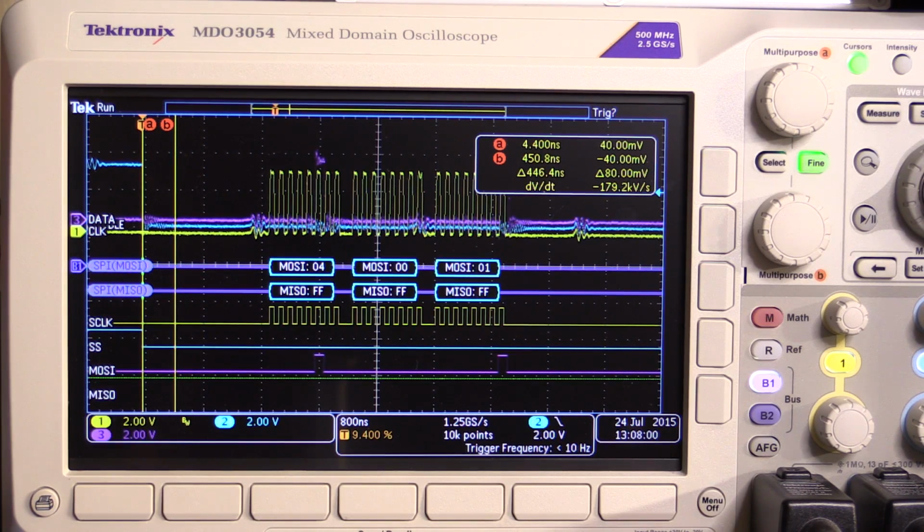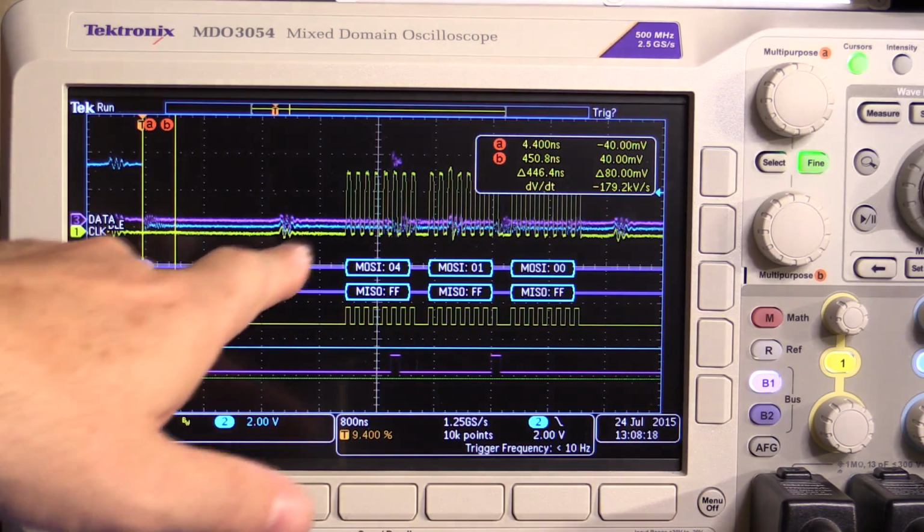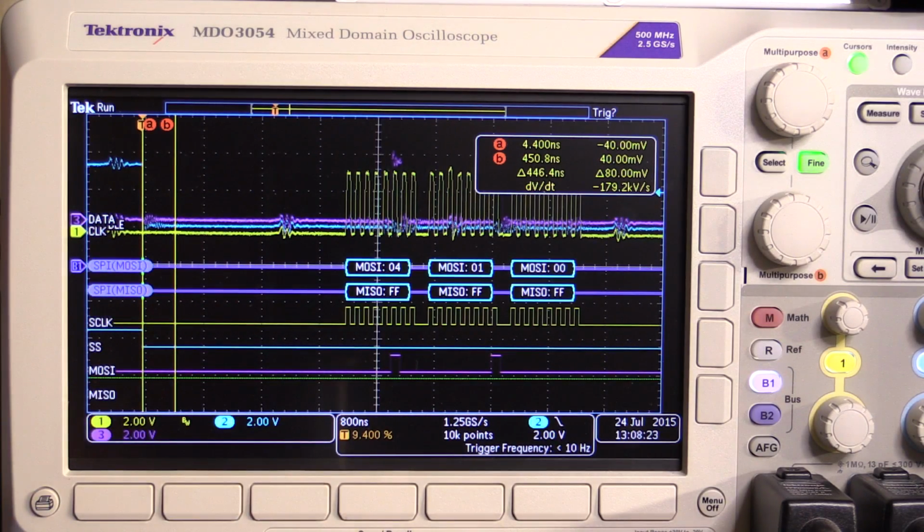If instead of 1, I now output, say, 256, it should jump to the other byte. I'll output that now. And there you have it. So you've got 04, 01, and 01. You can see there's a little bit of extra delay happening there. I'm not sure what these little ripples are that happen every now and again. I think they're maybe from the switch mode power supply or something like that. I don't have a huge amount of decoupling on this breadboard. If you're running this on the actual DAC8734 EVM board, you probably shouldn't get that kind of issue. As I said, you can freely use this software, or the Arduino Uno or LaunchPad stuff as you wish, or anybody else that gets this kit.